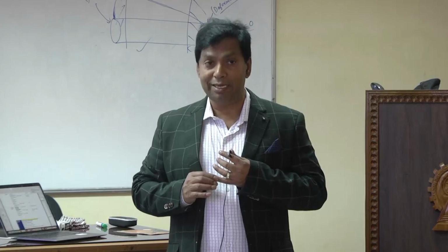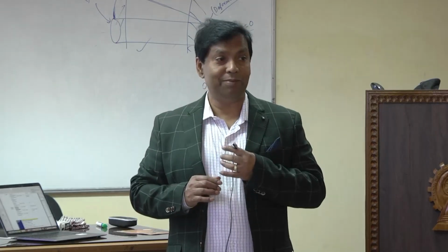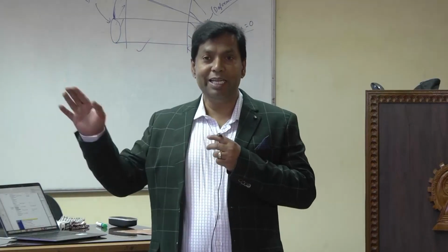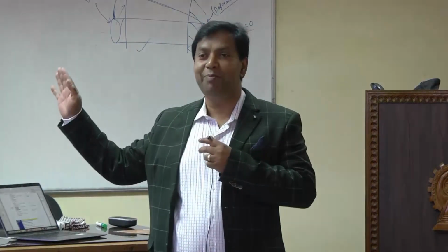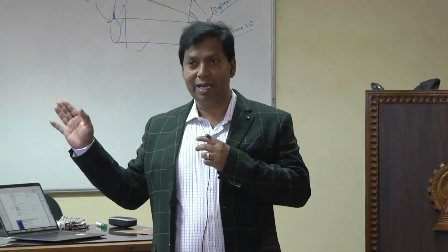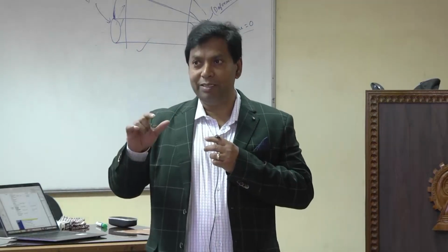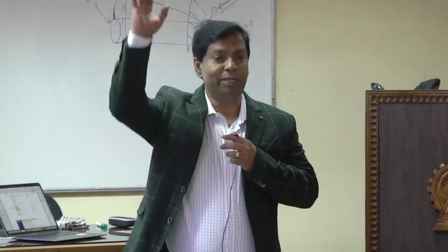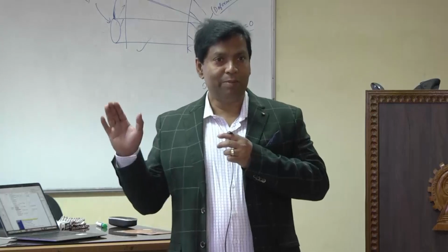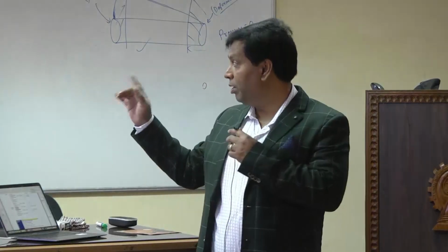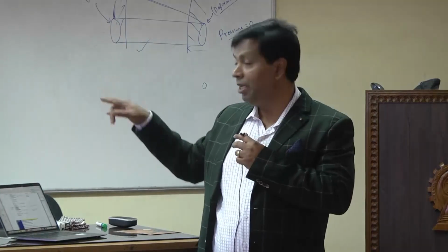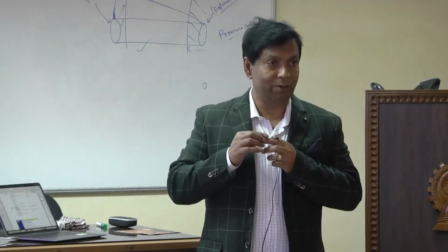But in industry, you can see that the default one is the K omega model. Industry uses the K omega model in every case, even laminar. They don't care about that because it is faster. They use a model, meaning they are not solving the whole equations, they are modeling it, making it simplified. But for research, we should not use it. Because he is very used to using it for the whole lung, that's why he used this one. But you can use laminar for your case.